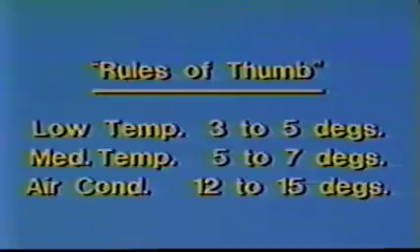There are a number of ways to determine the most desirable superheat setting. The method that continues to work the best is to follow the equipment manufacturer's recommendation. He has studied the question with all system factors taken into account. If, for some reason, the manufacturer's recommendation is not available, there are general rules of thumb that can be used. Lastly, you can select a superheat setting that does the best job of cooling while at the same time keeping other critical system readings at acceptable levels.